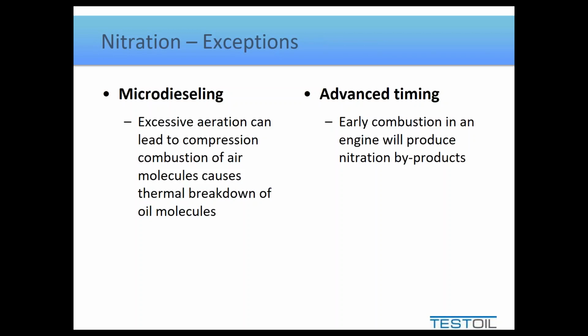They found that when they took buses that had been normally running diesel fuel and switched over to biodiesel, in fact they produced worse emissions and had less fuel economy. But by retarding the timing 1 degree only, they suddenly achieved slightly better fuel economy than previously and far, far better emissions. And it was discovered that this nitration effect is significant depending on the timing of the engine.